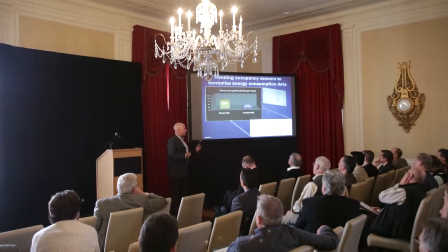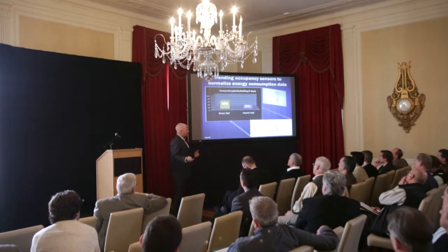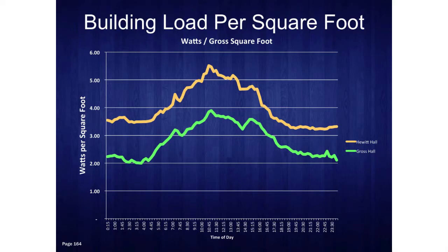That building utilization, how is that compared to another building on campus? Building load per square foot. Go back to the very opening topic. Yeah, it doesn't tell you a lot of information. Sub-meter that down and say, add my exhaust fan energy, my supply fan energy, my pump energy, my chilled water energy, and divide by building square footage. Compare two buildings on my campus.